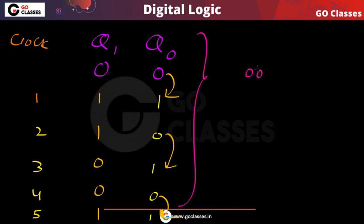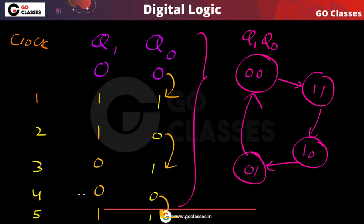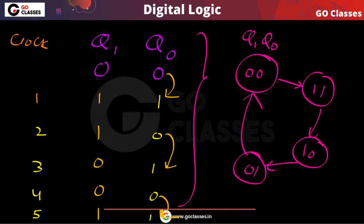Now you can very easily notice that this is q1 q0. From 0 0 you are going to 1 1, from 1 1 you are going to 1 0, from 1 0 you are going to 0 1, and from 0 1 you are going to 0 0. So this is the point. When you are doing this analysis, we are assuming that there is no propagation delay.